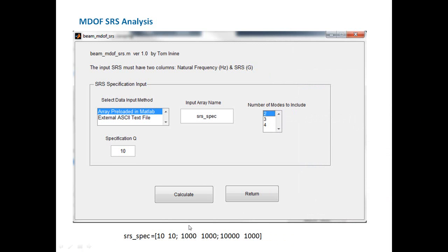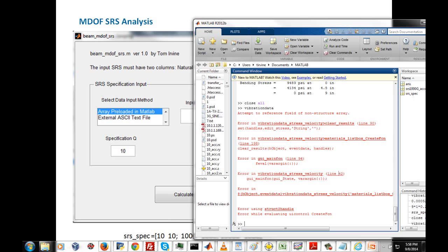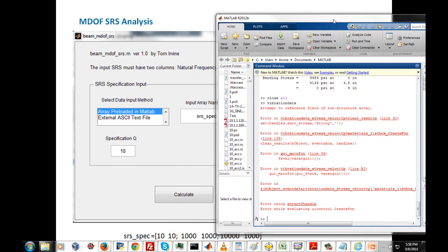This is just taking our natural frequencies from our normal modes analysis, and not even doing modal transient, but just taking the SRS and picking off responses from the SRS at our handful of modal natural frequencies, then calculating the equivalent pseudo velocities, accounting for the participation factors, calculating the resulting pseudo velocities, and then on to stress that way. So this is the really quick and simple method.